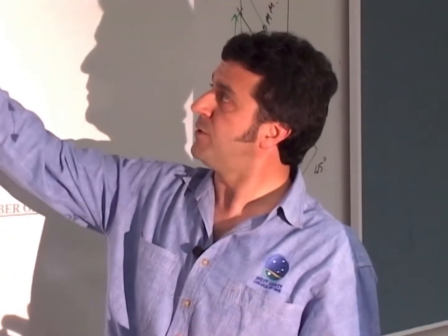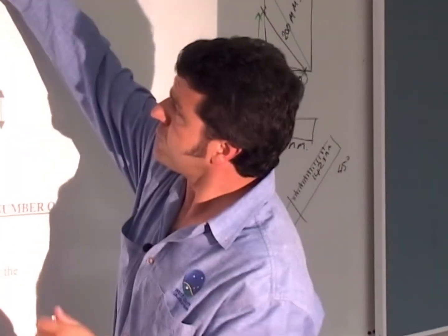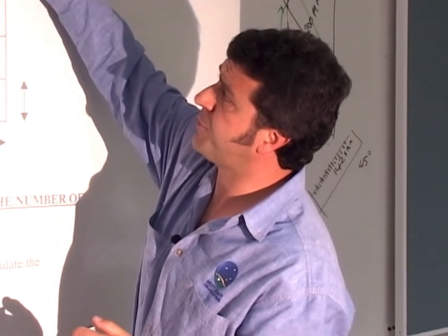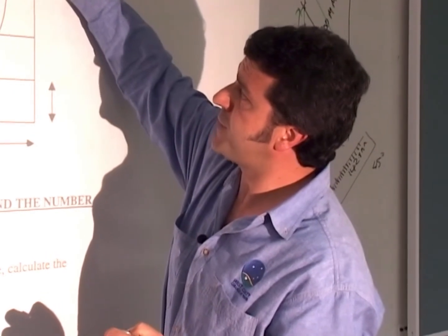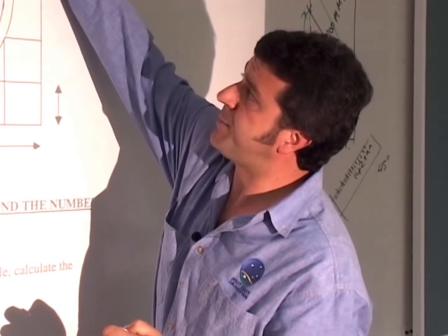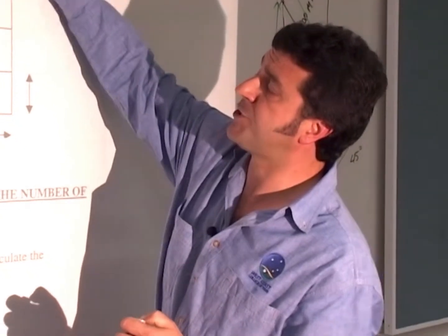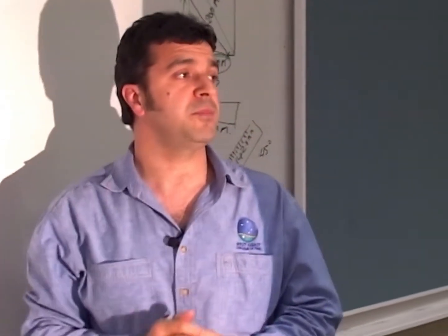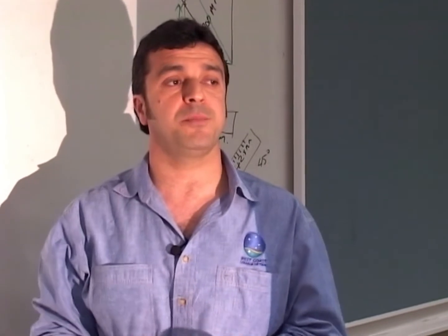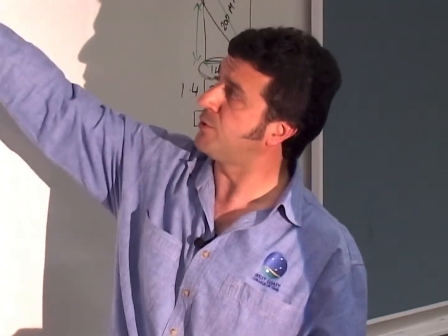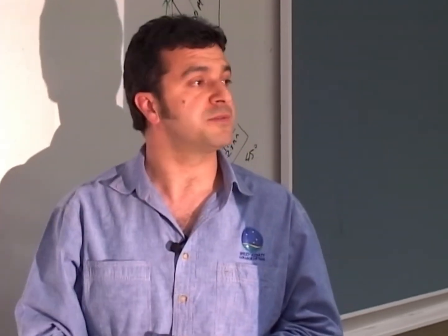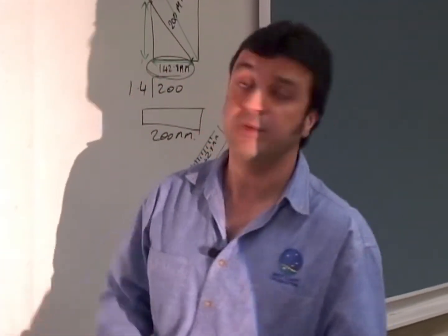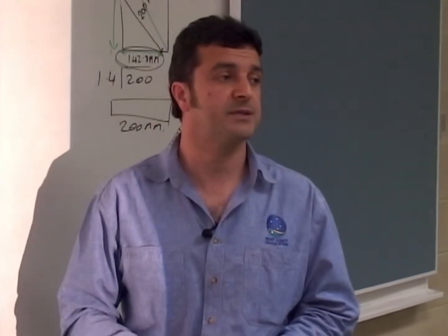So we're still going to use tile cutters to remove the majority, the biggest part of the tile I should say, and then we're actually going to use our round jaw nippers to get a circular shape. And we all know how accurate you can be if you take the time and you've got a nice sharp pair of nippers. We can achieve a beautiful contoured circular shape cut, and then we're just going to sand it down with a bit of sandpaper to give it a nice safety edge and nice and smooth. And that's pretty much all there's really involved, and it's not quite as hard as it may seem.